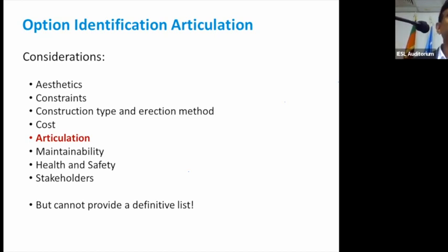It will move, right? How do you facilitate that movement? If you have a portal frame structure and everything is fixed, what would happen if you did not allow that movement to take place? You get high concentrations, and it will be an uneconomic solution because massive forces will come onto the substructure, to the piers, and finally to the piles.